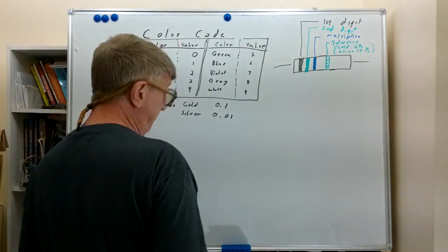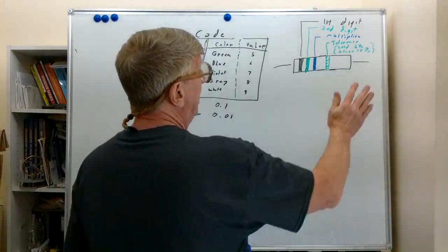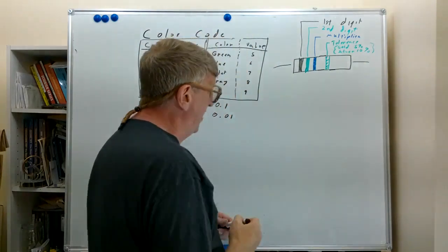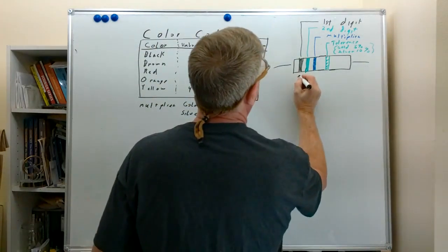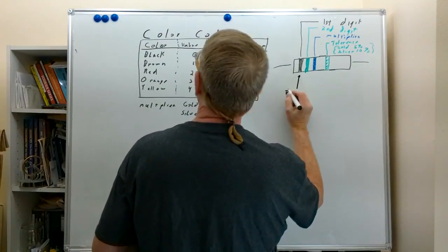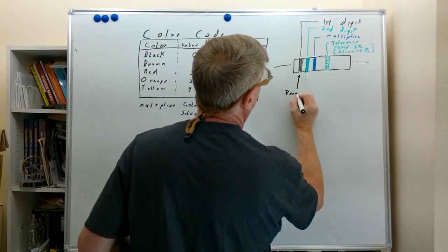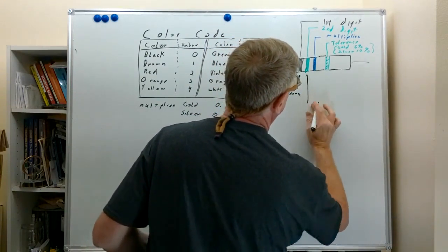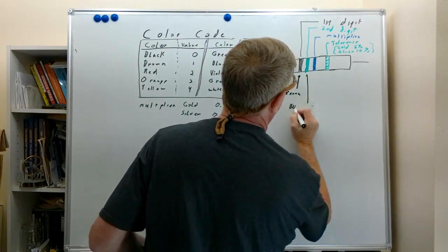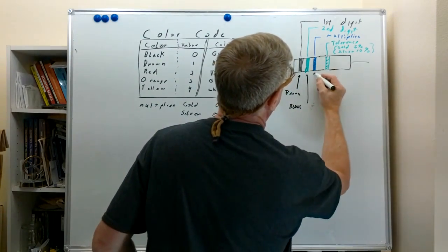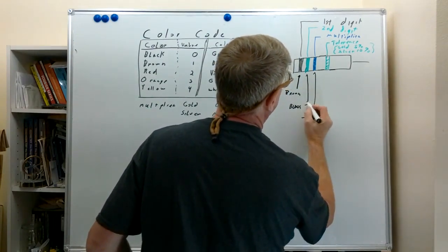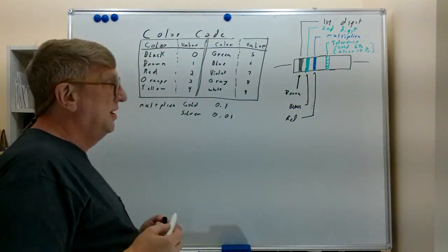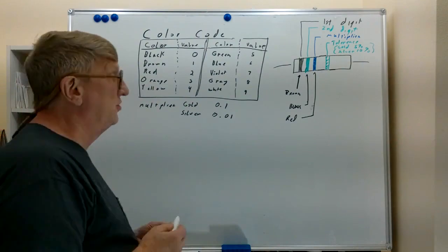And I've drawn a picture of a resistor here. Basically the first 3 stripes typically tell you the resistance value. If I had here a brown and here a black, and here a red, now how would we read those colors to understand the value of this resistor?